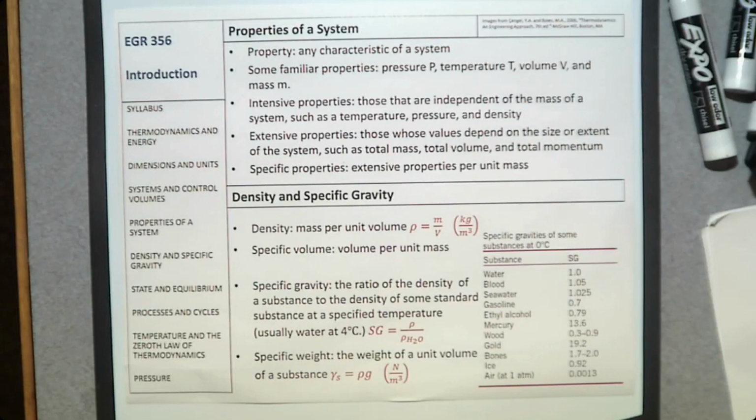Then how can we use only intensive properties? Because sometimes we have to use energy, volume, mass. Then we can simply divide them by mass and then use them in an equation. Okay? So that we can only use intensive properties. Those extensive properties that are divided by mass are called specific properties. So if you divide energy by mass, it becomes specific energy.